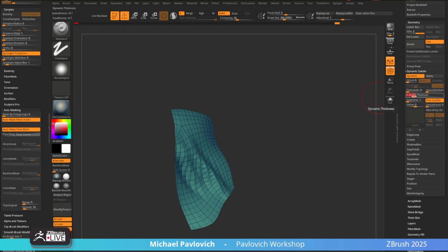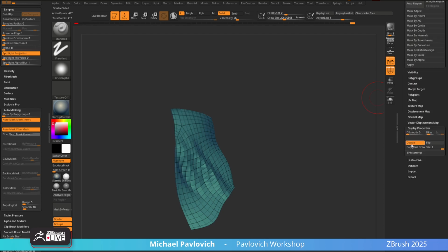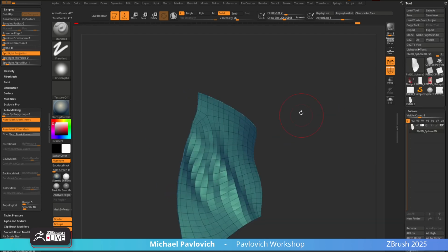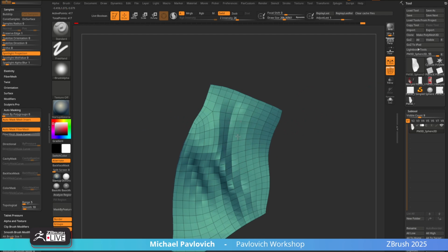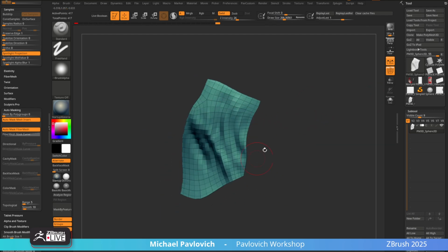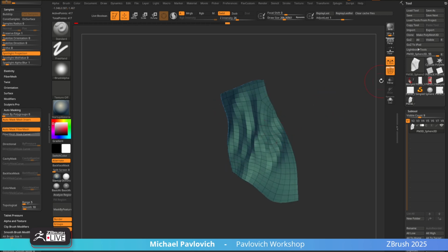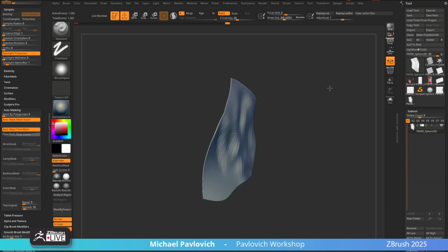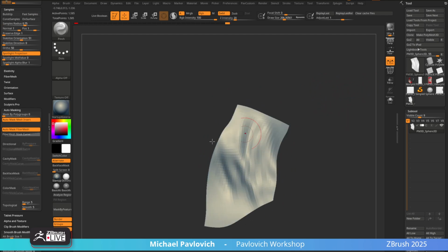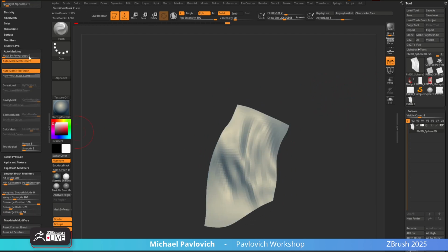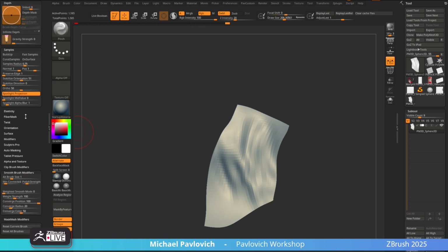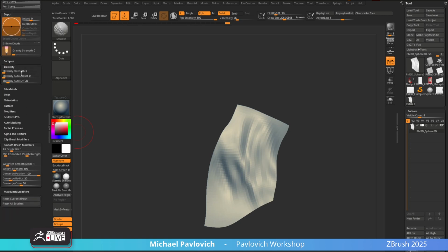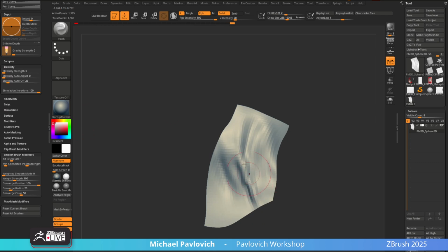And like we did earlier, just turn on that thickness. And now we don't even need Double turned on. So now it looks like you're sculpting on a thick cape, but you're really not. So that way you can kind of get a feel for it. And again, hit Control D to subdivide. Go through here, use our pinch brush with elasticity turned on like we did earlier. Brush, Elasticity, simulations up to 100. So you can go through here and you can simulate cloth as you're pinching and stuff.